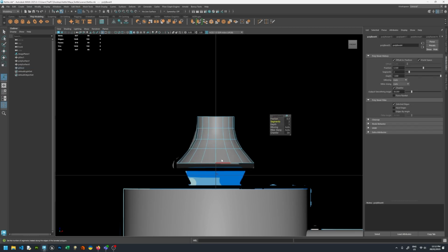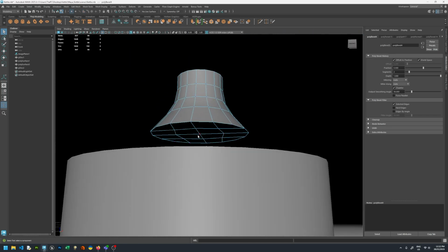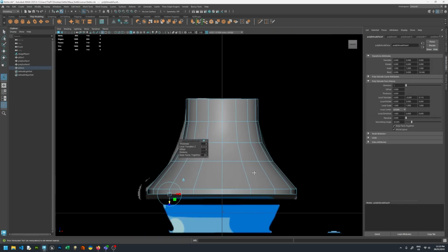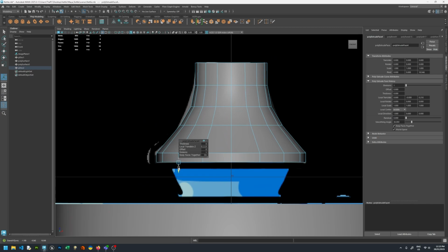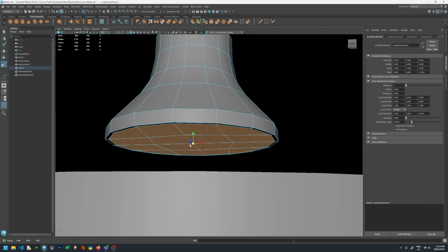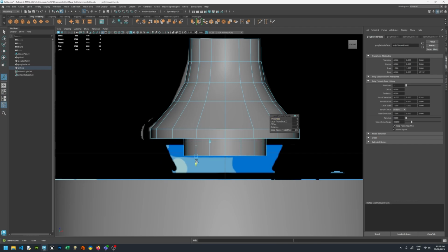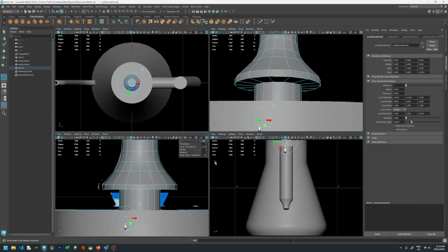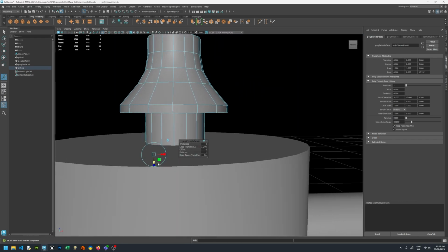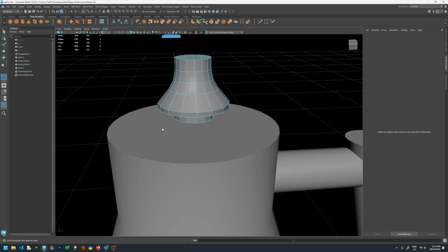Okay. And then the bottom, I'll just extrude out so it's got a bit of a flat. Same thing, grab the vertex, Control F11, and extrude that down. All right. We'll then extrude it again, scale it inwards, extrude again, and scale it down. And that's the handle. But I should delete the face first before we intersect it.